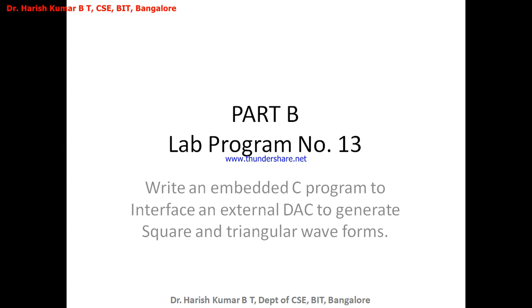Now before I explain the external DAC, first I'll focus on the internal DAC. LPC2148 has got an internal DAC as well. The internal DAC of LPC2148 is a 10-bit DAC. There is a built-in DAC present inside the LPC2148, and that is the 10-bit digital to analog converter. So the external DAC which we will be interfacing with the LPC2148 later is an 8-bit DAC.